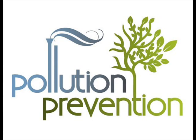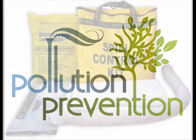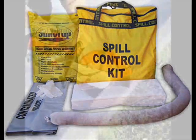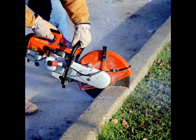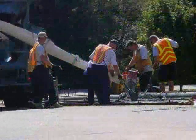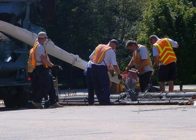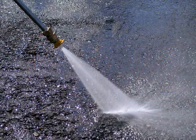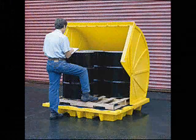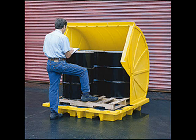Additional pollution prevention for public works activities. Have spill kits on select vehicles for quick response. During concrete cutting, plug the storm drains, divert flows, clean up any residue, and dispose of properly. For street, island, or boulevard washing, it is best to minimize this activity, especially if chemicals are used to wash the concrete or asphalt. Secondary containment is needed for all bulk storage of chemicals on a construction site.